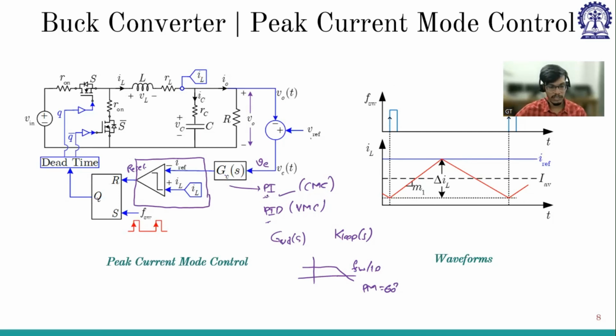So for that reason, only PI is sufficient to do this. So if only PI is sufficient, why go for PID? Why would we implement a complex thing? So that's why only PI is sufficient. And derivative action, we sometimes don't use direct derivative. We use load current feed forward, which will also act as a derivative, and that will be discussed in the upcoming sessions.